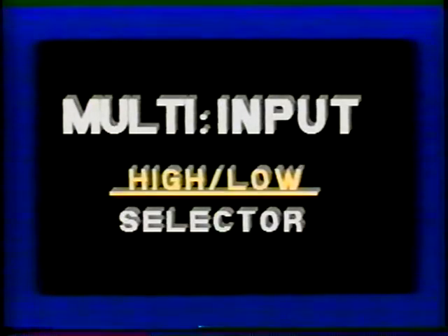The next selector relay to be discussed is the multi-input high-low selector. The multi-input selector relay is designed for use in pneumatic control systems where the application requires the comparison and transmission of the highest and/or the lowest of multiple pneumatic input signals.